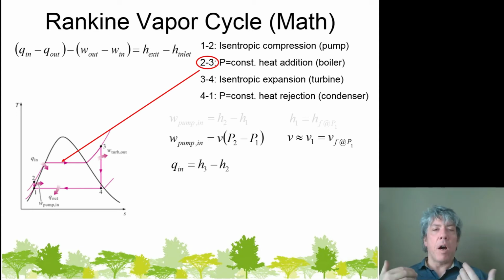It's taken care of automatically by the enthalpy tracking all of the energy in the liquid and the vapor. Now, you're going to look up these properties in different areas. You look up the enthalpy in state 3 over in superheated tables, and the enthalpy in state 2 you would look up in compressed liquid tables if you have them. We'll go a different way because we don't. It'll be a good approximation. I'll show you that in a second.